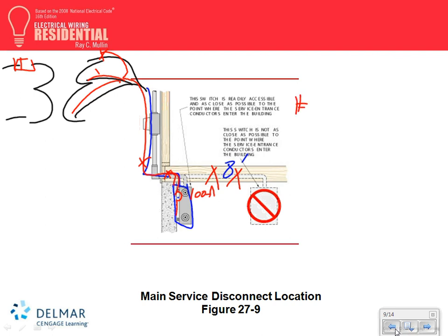Number 6. It's number 6 or number 8, which is rated how much? Number 6 can give you 50 amps. You're looking under the 75 degree column, right? Minimum. Yeah, number 6. And then for number 8? The 6 is the aluminum. 8 copper and 6 aluminum. 8 copper. Let's do the 8. How much current can 8 carry under the 75-degree column, 60-degree column? Oh, 40. 40 amp.